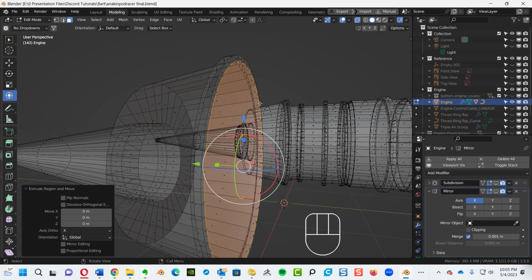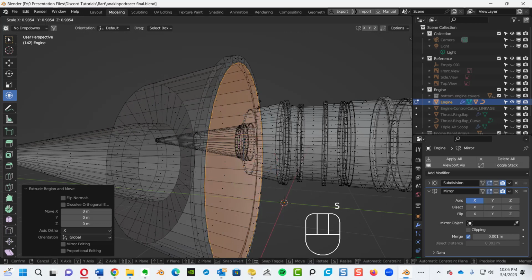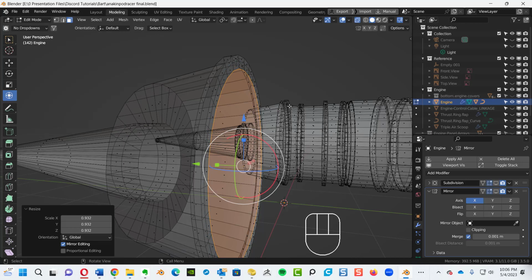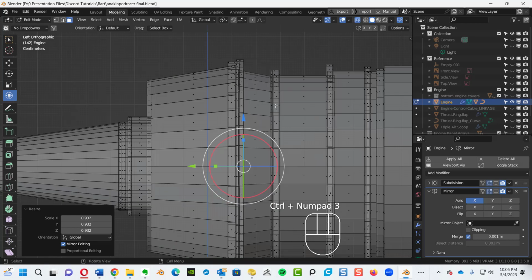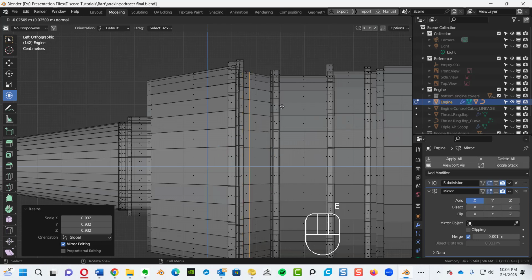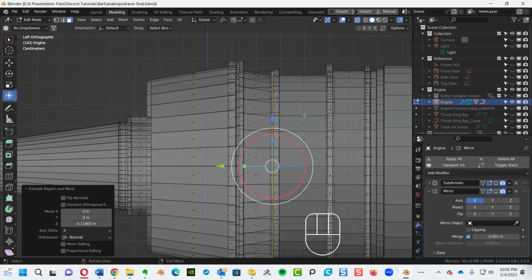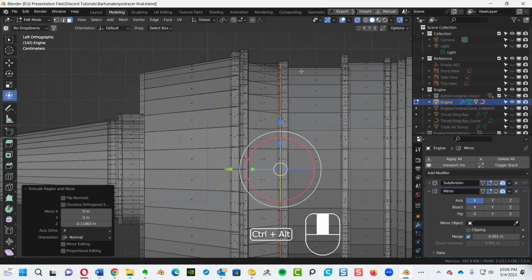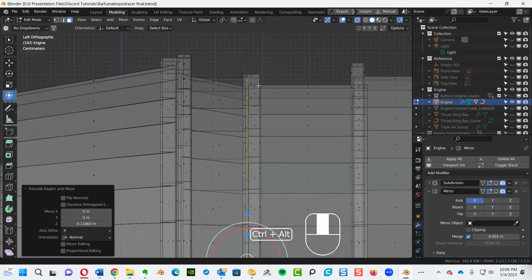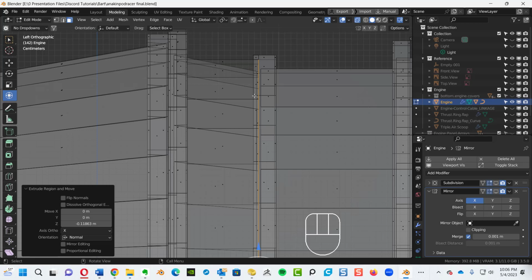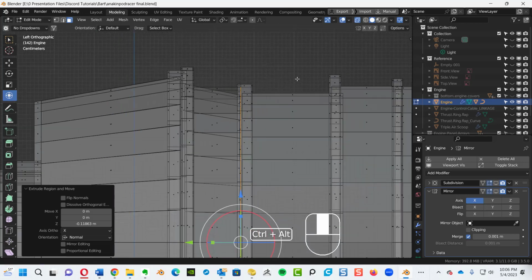and we're going to bring this in a little bit. So S key for scale, bring it down a little more, probably right about there. Okay, that looks all right. E key, there we go. Bring it to here, right about there. Because remember, the front of this first line here is basically an extrusion of an edge. The actual solid piece is right back where this sits.